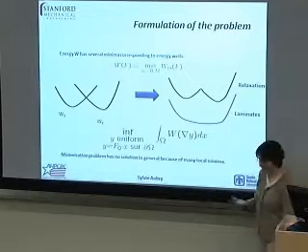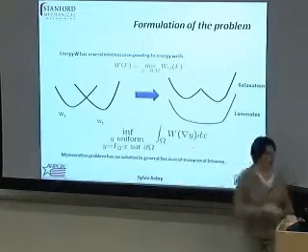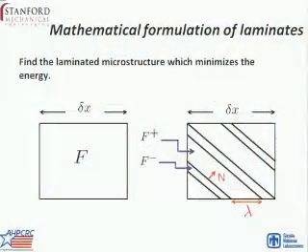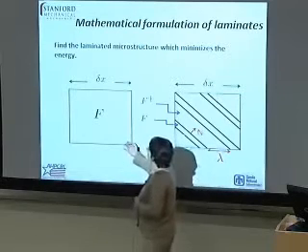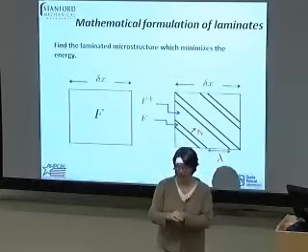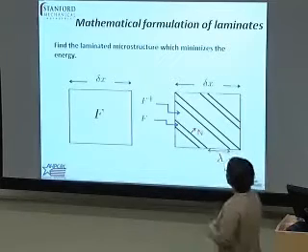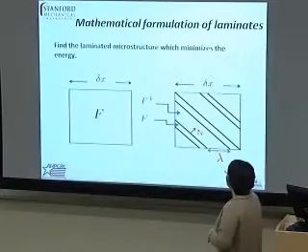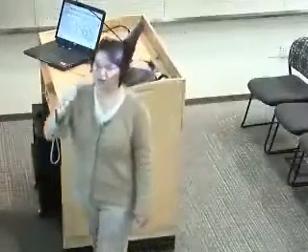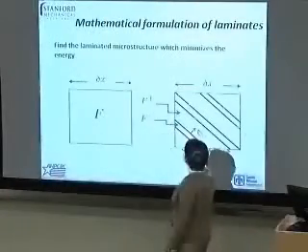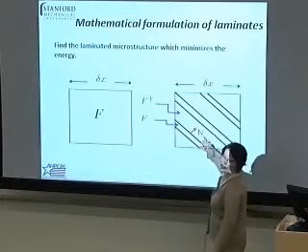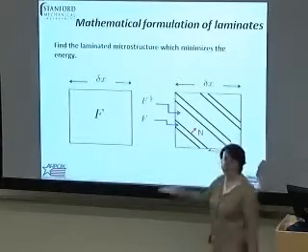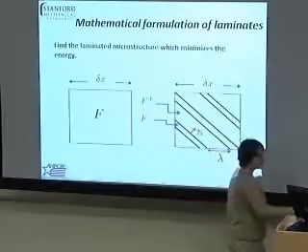So using laminates, you can define another energy, which is going to be close to the one you want to solve. And the way it works at the microscopic level, again, is the following. You have your deformation gradient F for a given little space in your system, and you replace it by a rank 1 laminate, which is going to be defined by, instead of F, F plus and F minus. And F plus and F minus are going to be defined such that you have a direction of lamination and you have a proportion. So there are similar ideas to topology optimization.